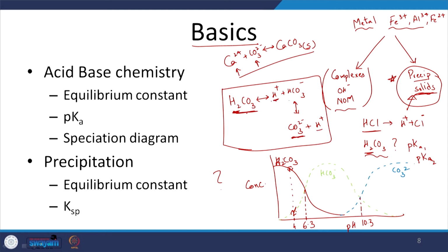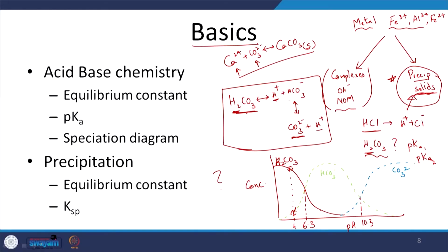So, at pH 4, very little will dissociate, less than 1%. So, when I add H2CO3 at a pH of 5.3 or less, most of it will stay as H2CO3, and it will not affect the pH of the system, because enough H+ can't be released.